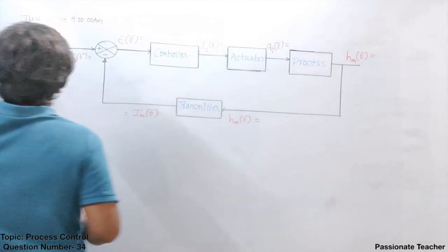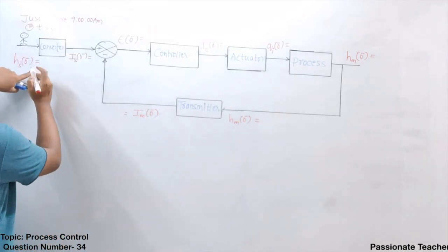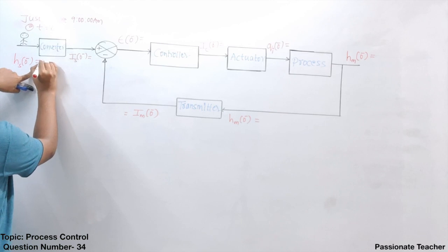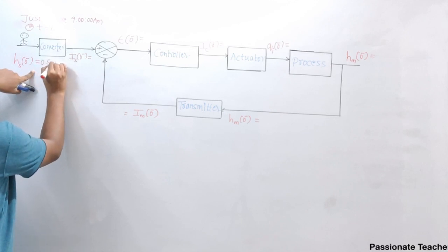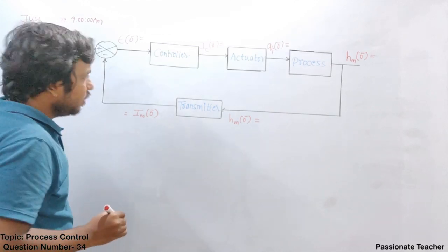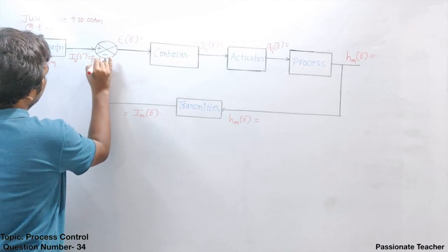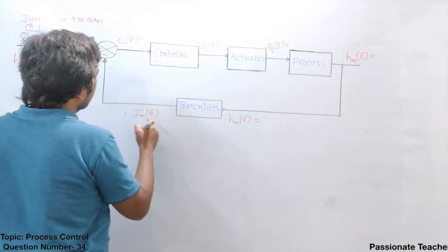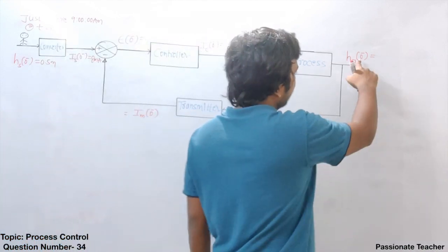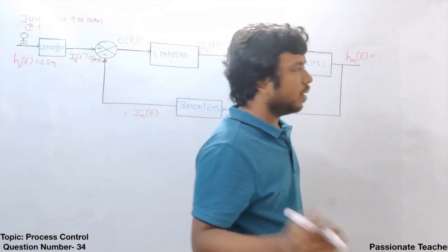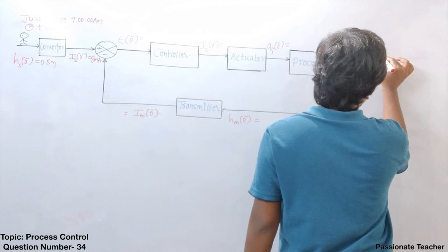So what does it mean? Just before 9 am, our set point is actually 0.5 meters. This is what we expected earlier, right? And corresponding to that, it is generating 8 milliampere current. Even we know that just before 9 am, the water level inside the tank is also 0.5 meter.